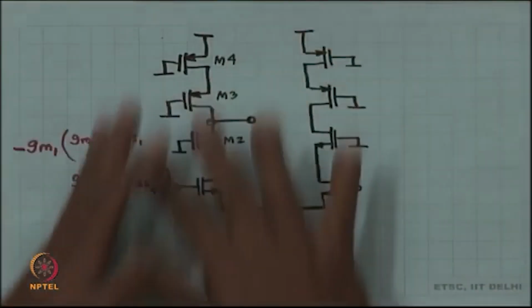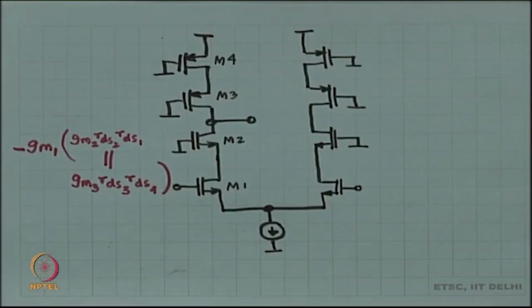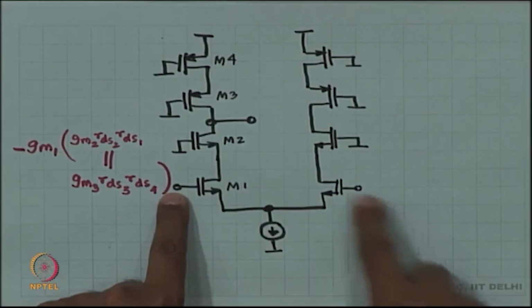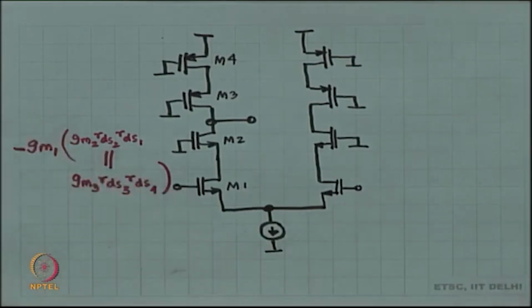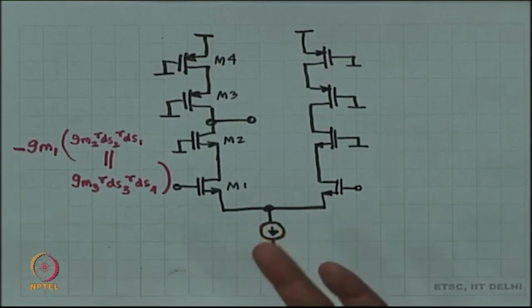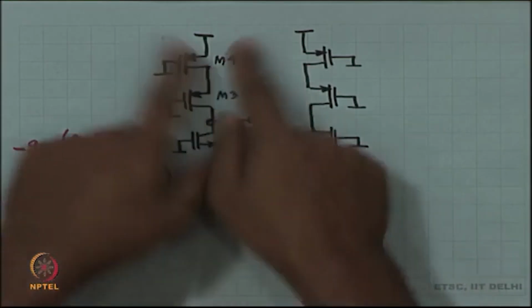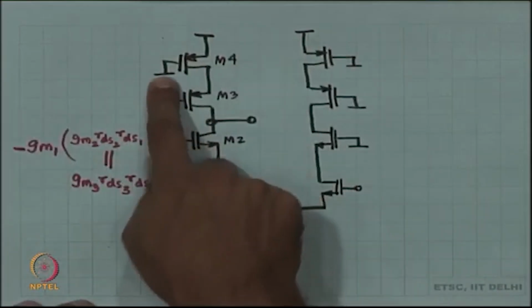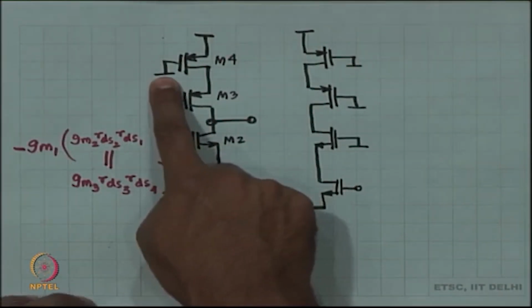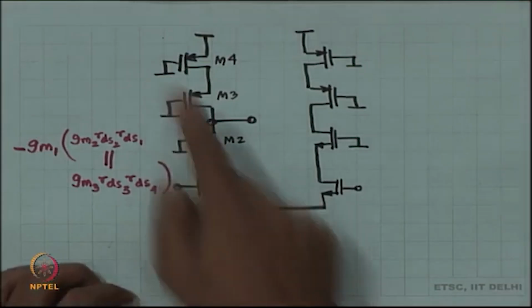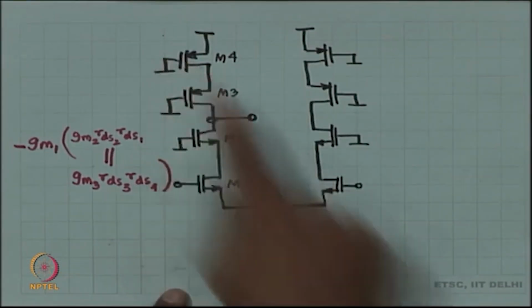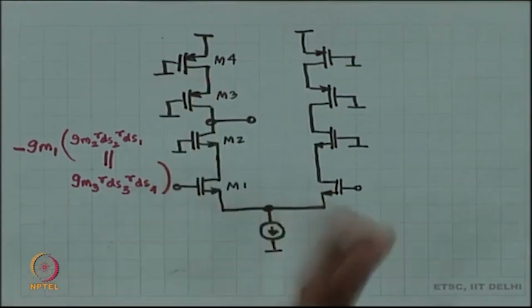All right. Now, this is still the small signal picture. You are going to apply V in positive over here, V in negative over here in the small signal. This is still the small signal picture, and now you have to incorporate the operating point conditions. How will you incorporate the operating point? I mean, are you going to connect this to ground actually? No, right? You are going to connect it to just the right voltage such that half of this current flows through it.